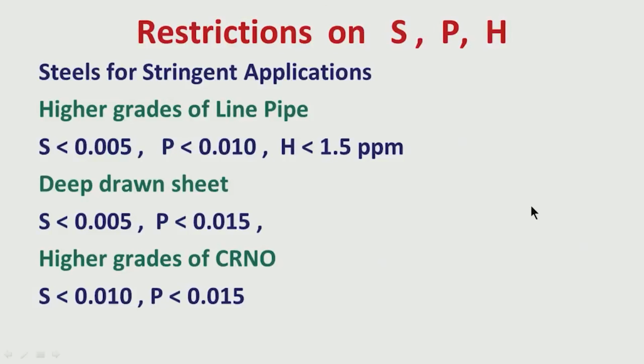One thing I must mention here, hydrogen analysis, because hydrogen's atomic number is very low, the lowest. So, the diffusivity is also very fast because the size of the atoms is very small. So, hydrogen, if you keep it even at normal temperature, whatever hydrogen is there in steel will try to diffuse out.